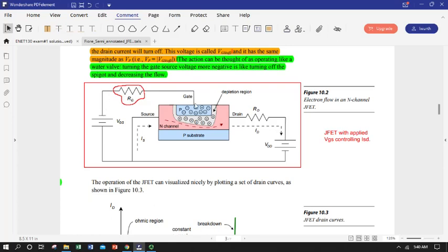So our gate has a negative voltage applied to it. In our p-type material, remember, we have a lot of positive majority charge carriers, a lot of holes. We've doped that p material with that trivalent dopant. We've effectively introduced a lot of positive charge carriers. Well, when we apply a negative up here at the metallized contact, all those charge carriers are going to go stampeding up towards the contact and away from the junction.